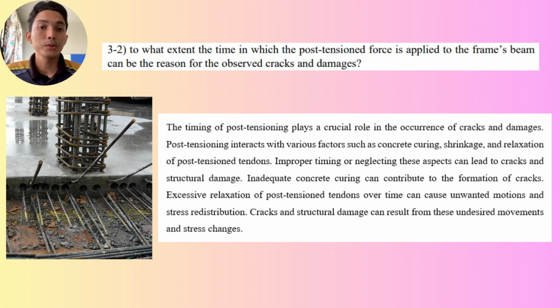The timing of post-tensioning is crucial because it interacts with numerous elements such as concrete curing, shrinkage, and post-tension tendon relaxation. Improper timing or failure to address these aspects might result in cracks and damage. For example, if the concrete is not properly cured or if the tendons relax excessively over time, it might cause unwanted motions and stress redistribution, resulting in cracks and structural damage.